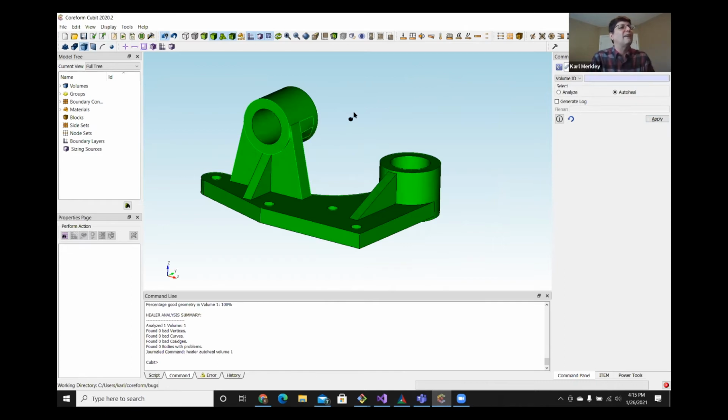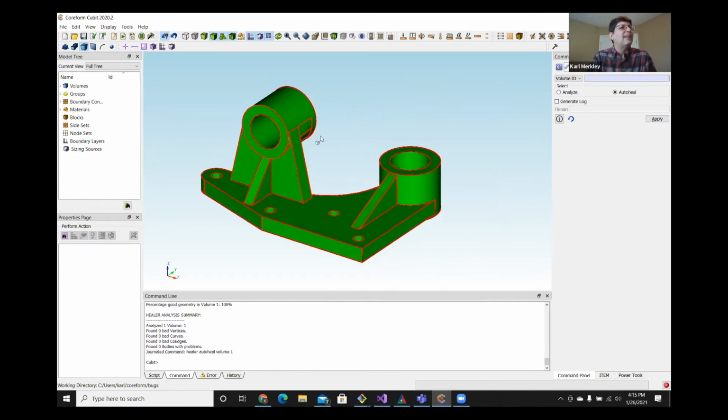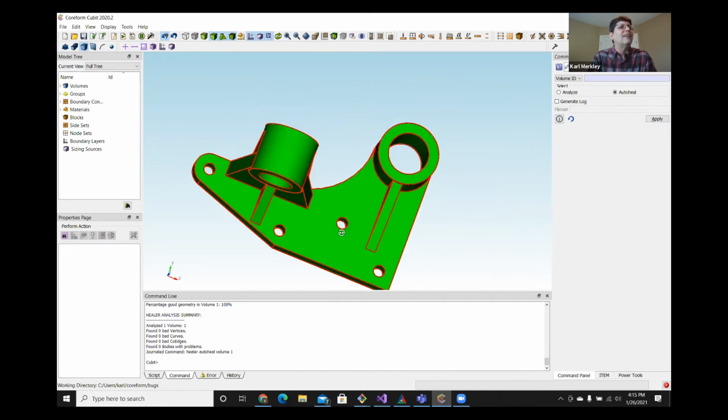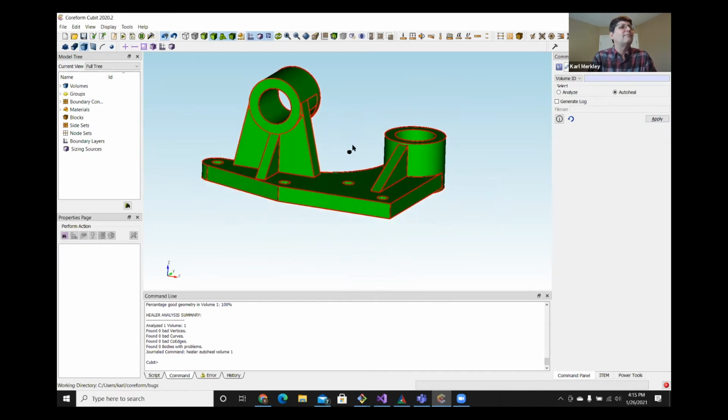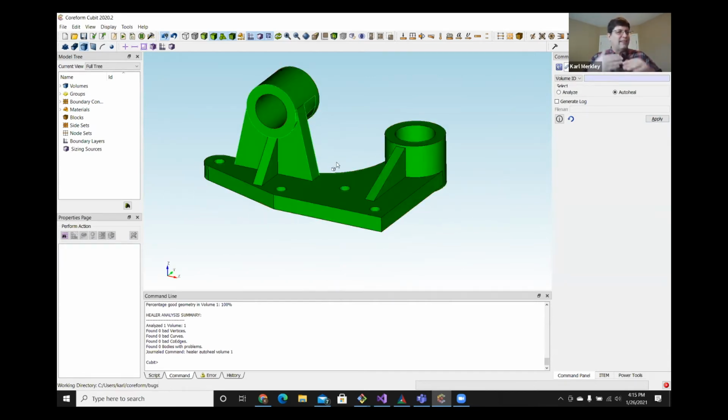But I wanted to show that because, when we get to the end, we'll compare what happens at these tangencies with what happens down here at these other tangencies and just look at what happens. So the first step then is this cleanup. We go through, we clean up our model, we get rid of some of those small features. In this case, we blunted some tangencies as well.